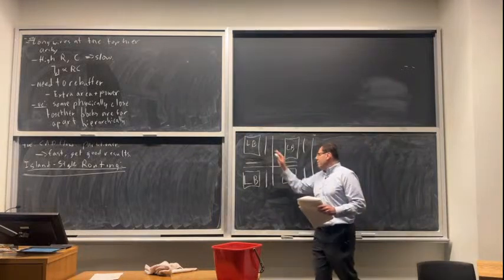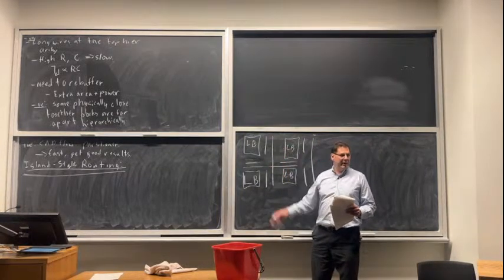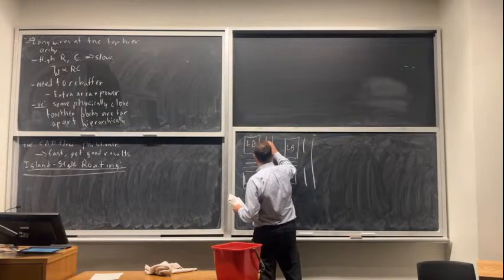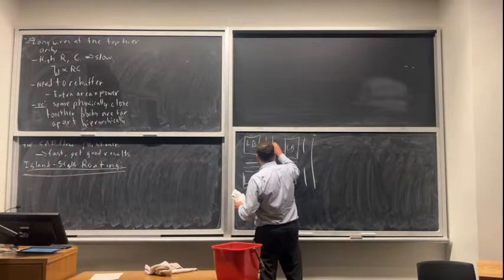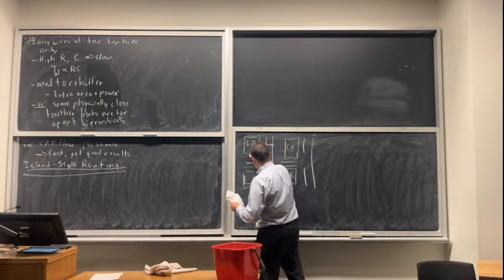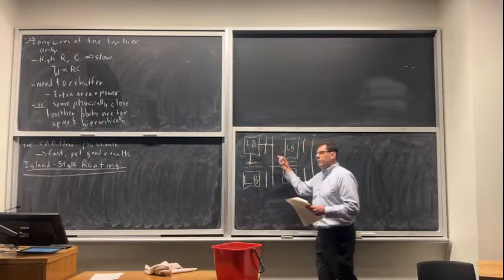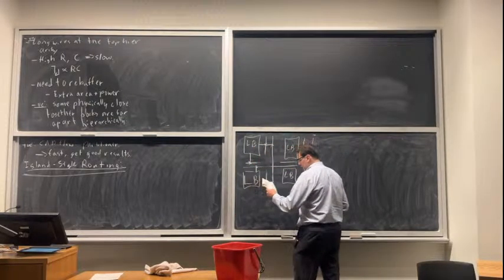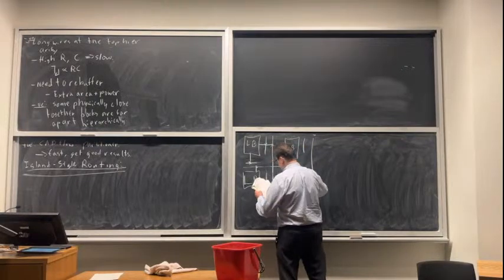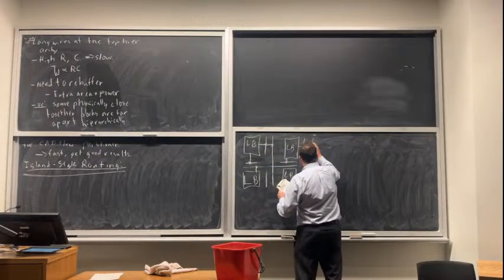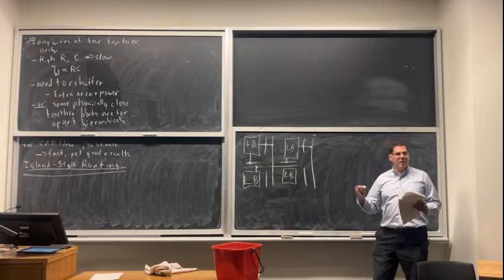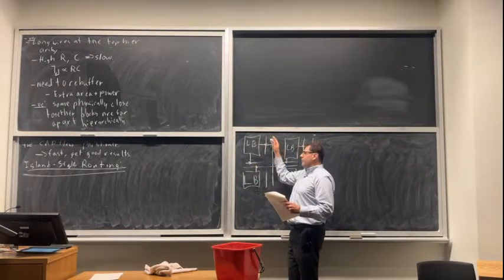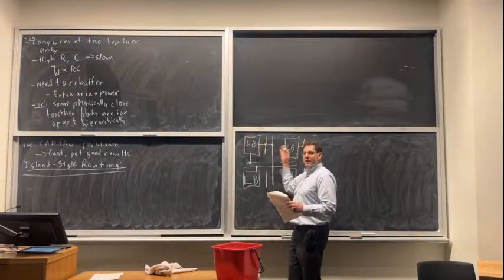And in between the logic blocks, we put prefabricated routing wires called routing segments. And then we put programmable switches to allow us to connect the outputs of these blocks and the inputs of these blocks to some of the wires that go past them. So I'll draw a few programmable switches there. Usually we do this in a regular pattern to make this easier to lay out. So we'll make a layout for one tile and then repeat it over and over again to get our pattern.